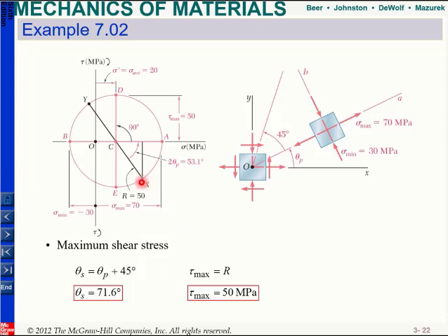Also, when you move your x to D, what's your normal stress? The coordinates of my point D are basically my average and then minus tau xy. So the normal stress when your shear stress is maximum is given by sigma average, and we already calculated that it is equal to 20 megapascal.